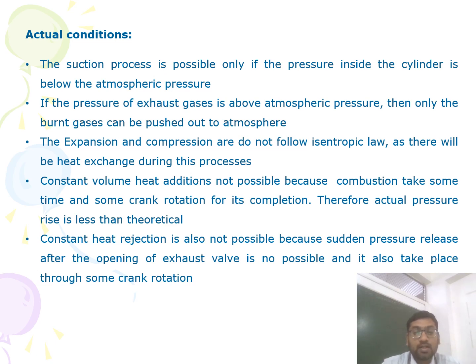Fourth, the constant volume heat addition is only possible because the combustion takes some time. It means some crank rotation for its completion. So therefore, the actual rise is less than the theoretical. As we know, combustion is a natural phenomenon. It requires some time to complete.